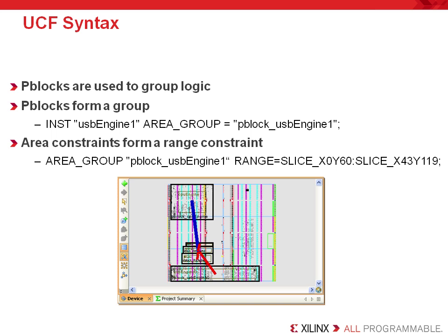Area group constraint is a design implementation constraint that enables partitioning of the design into physical regions for mapping, packing, placement, and routing. The area group is attached to logic blocks in the design, and the string value of the constraint identifies a named group of logical blocks that are to be packed together by the mapper and placed in the ranges, if specified, by the place and route.